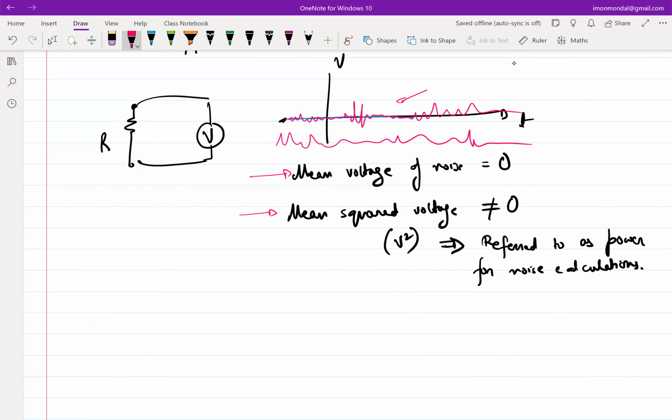So that apparently helps us in making the statistics of noise, right? So how does it help? It basically says that you can do autocorrelation between these multiple waveforms at different points of time, and then you take a Fourier transform. Do you remember what you get if I do an autocorrelation and a Fourier transform? Power spectral density, right? So if you do the autocorrelation of an ergodic process, it takes out T totally. The time goes off.